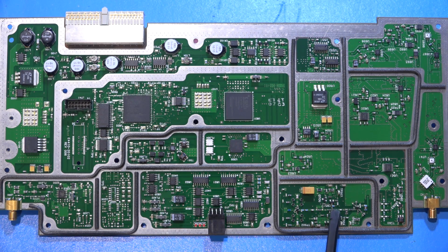It has some leveling, it looks like, and then it goes into another identical transistor, this time being used as an amplifier. That's not surprising. You can of course build a VCO from a transistor or an amplifier from it, depending on how you put matching networks around it. The output of that goes over here and through 1, 2, 3 filters to make sure there are no other harmonics, and then you need to double it.